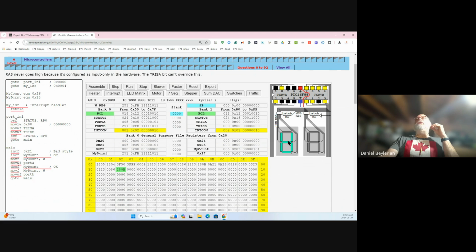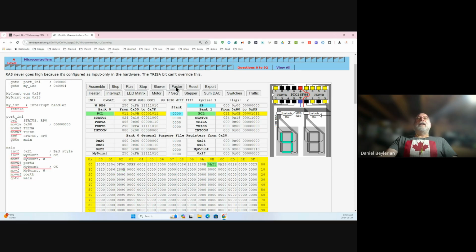So maybe what you should do is, when you're dealing with these steps, step through them one at a time. Come on, give me something else. Ah, okay, look at that. Now 0 and 2 are off. So now I know that that was 2 and this is 0. If you start playing with this step by step, you'll start to know which pins are controlling which segments. So here we go. What if I was to make it actually run and made it go faster?